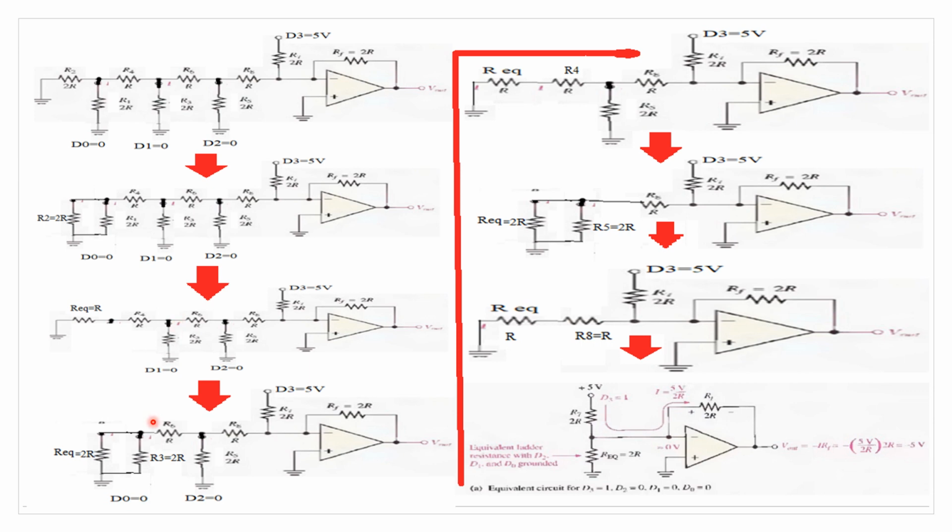Up to this much there is no change. Then this 2R will be parallel to this 2R. Hence the effective value will be half of the resistor, that is half of 2R, that is R. Now the circuit can be drawn like this. Equivalent resistance equal to R, remaining portion like this: R, 2R, R, 2R with a 5 volt, then this inverting amplifier portion.